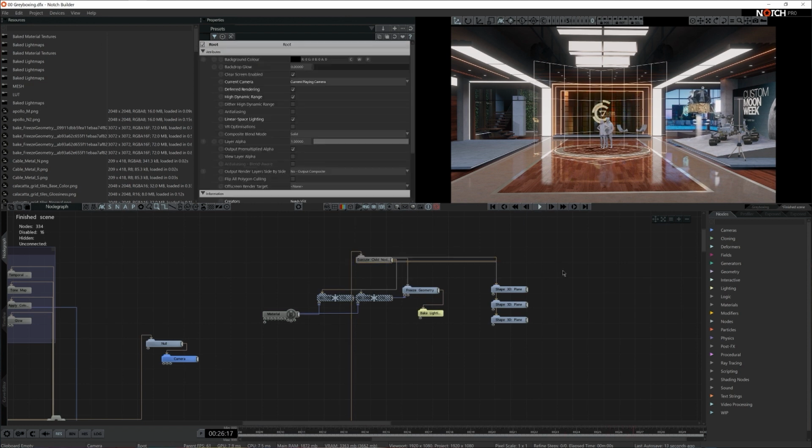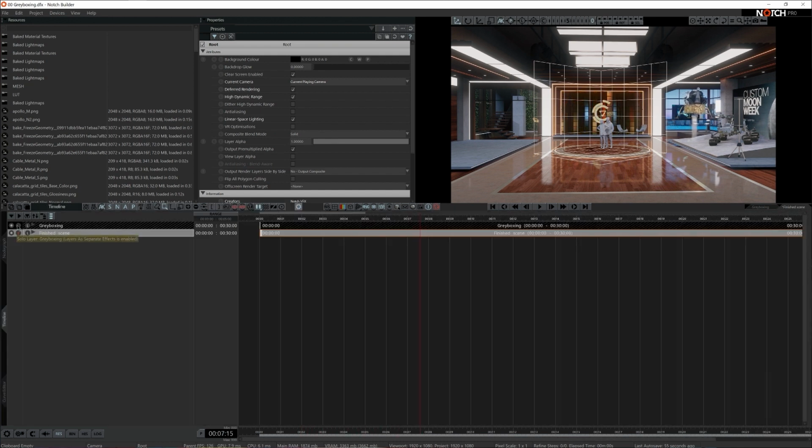So why is it a good idea to add these elements to the scene? Well, adding them enables you to scale your virtual content correctly, as well as ensure that you're framing shots from the position the camera can reach. And it allows you to see the distances between the camera, the subject, and an LED screen, which helps you with the sense of depth. In general, it's essential to build your scene to correct scale, as virtual production depends on the 3D world matching the scale of the real world.